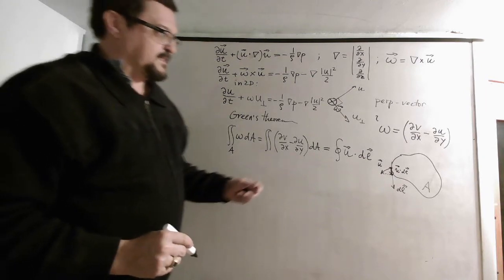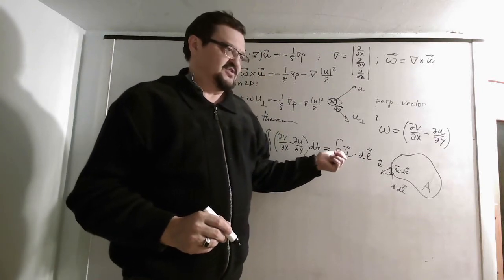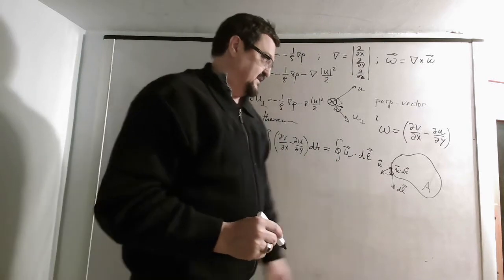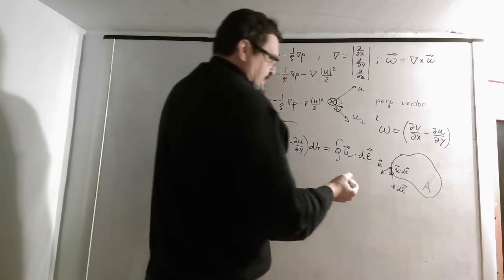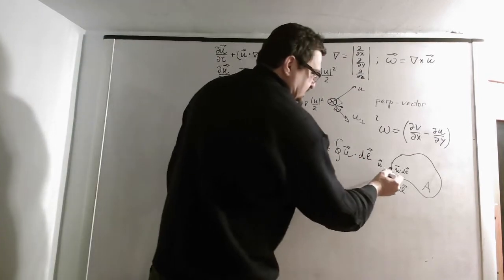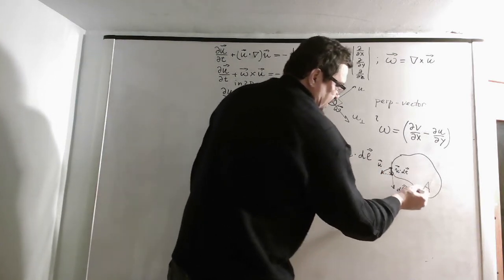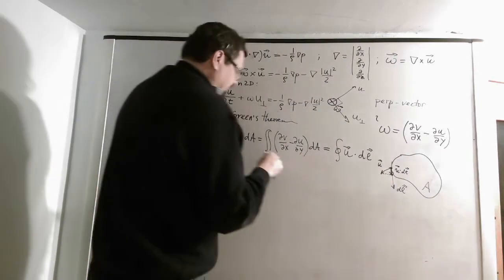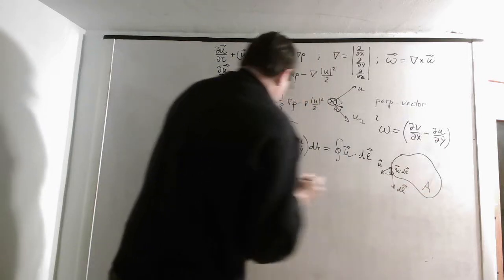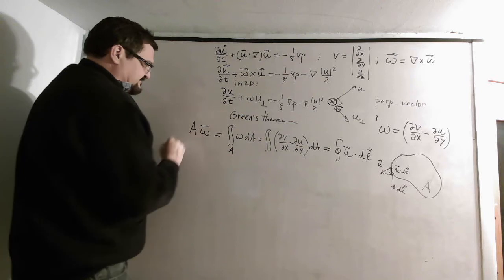Okay, so what we wrote before can actually be written in a Cartesian grid, the expression that we used in the previous lecture, but generally it's like this. It means that it's just the component of the velocity vector projected onto this boundary and integrated along that boundary. And this equals the integral of the vorticity in that area, or some average vorticity of that area times the area.